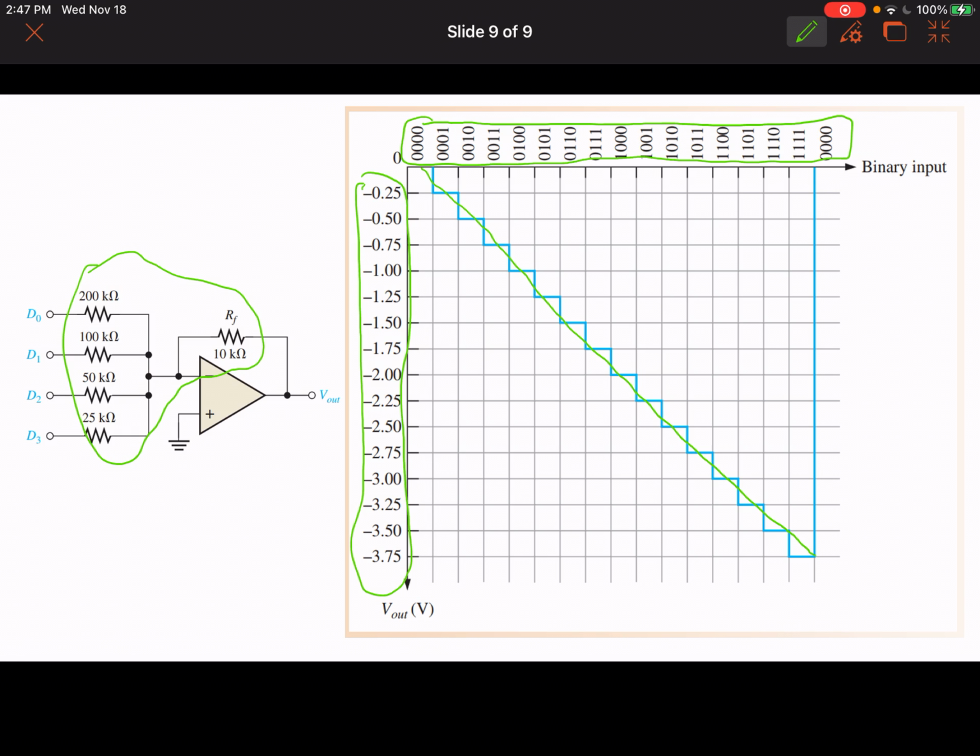So you can continue with this if you start to decrease the voltage in this manner, in the manner that is shown here. Or you can draw a sinusoidal voltage. So you have to select the proper bits to turn on and off at specific times, and so on and so forth. So basically that's how you use this summing amplifier as a digital to analog converter.